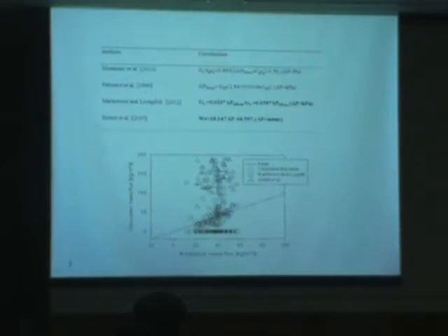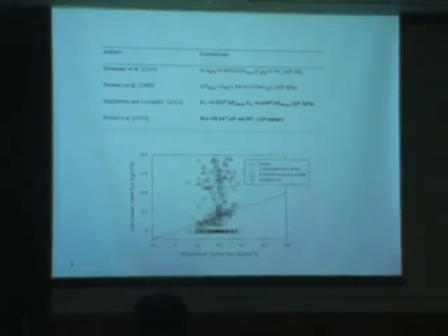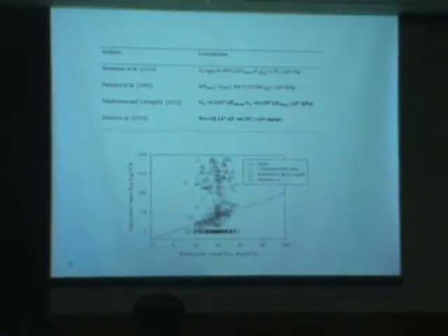They only offer the delta P of the riser horizontal point. Markström and Potier offer the riser pressure drop. So we compared our data with their correlations, and it can be observed that the Markström correlation underestimated while the Potier correlation overestimated the experimental data.